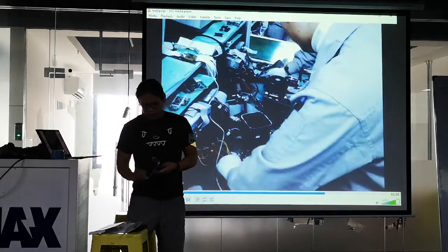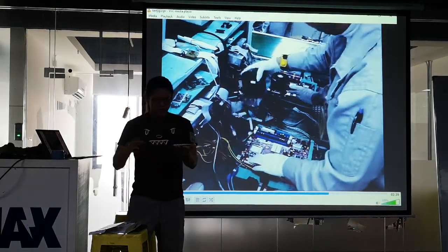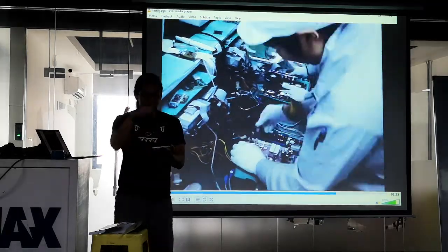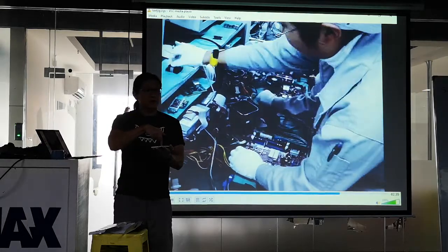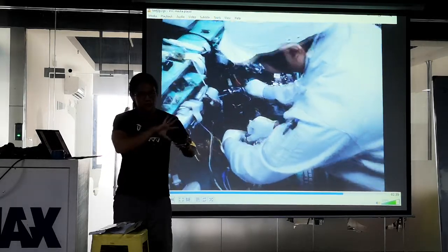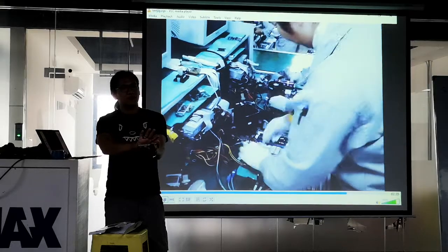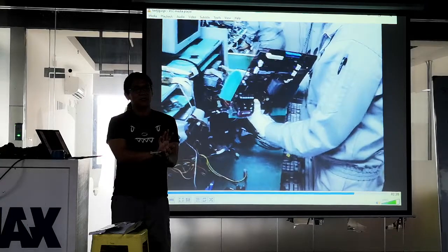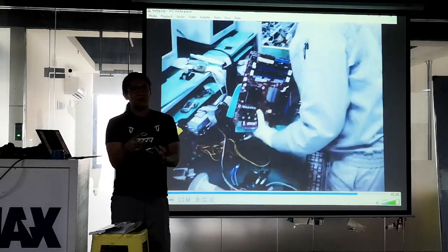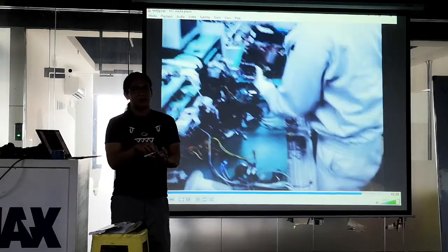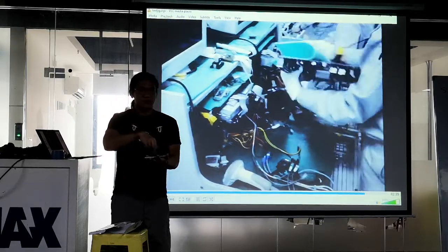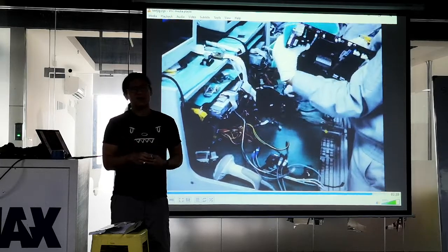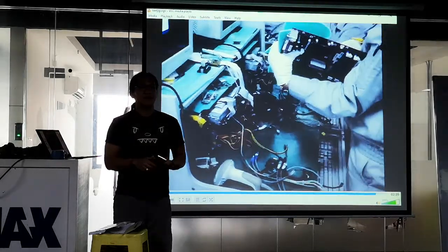A worker would just put the phone down into the machine, and then these little robotic arms would come up and plug in all the ports. A little silicone finger would come down and hang out over the display. It would seal itself into this RF chamber, and in about 30 seconds to a minute, it would test every feature of the phone: the camera, front, back, the LED. They had another camera that would check for bad pixels, RGB bad pixels, all sorts of stuff. That tester cost $1 million to develop.